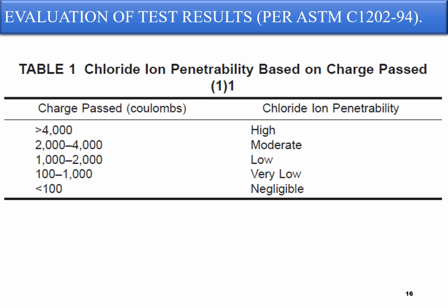So always for important structures, the RCPT value is at most in the range of 2000, and anything above 2000 is not advisable for a particular grade of concrete, when the durability of the structure or element is to be high, to the tune of say 50 years or 100 years or 120 years.